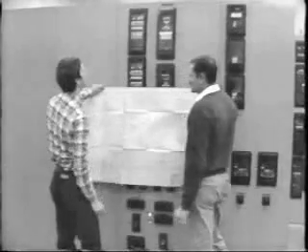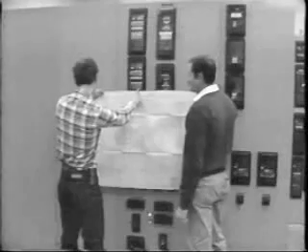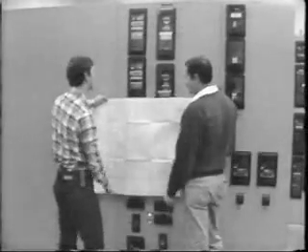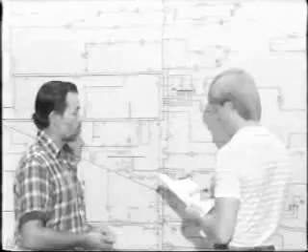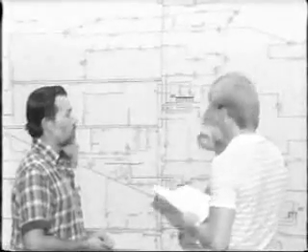But why is it necessary to go back and analyze faults after they happen? Well, this is done for two basic reasons. First, to check that the relays and breakers are operating as intended, and second, to explain any misoperations and predict any future problems.